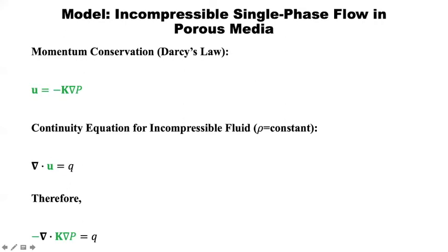So we'll just substitute it here, and in the last equation in this slide, we have what? It's an equation of second derivative. We have a derivative here, which is a gradient, divergence, and another one here, and p. So this equation is a single equation in one variable, right? Yes. So we can solve it to find pressure.